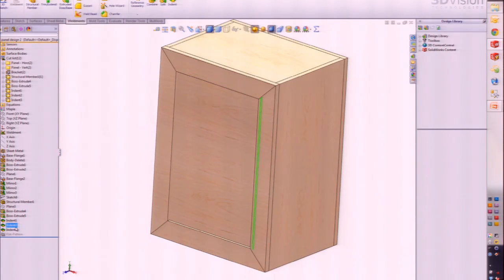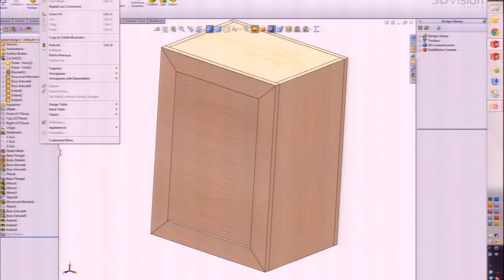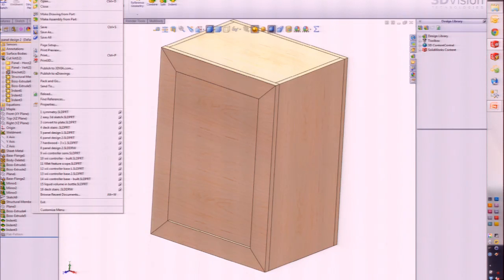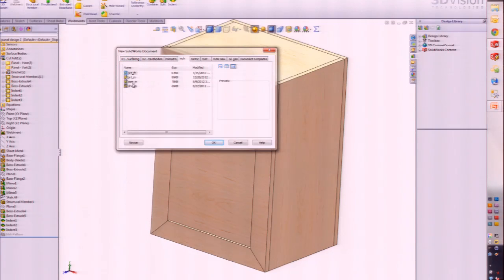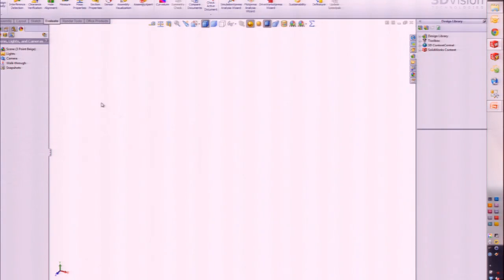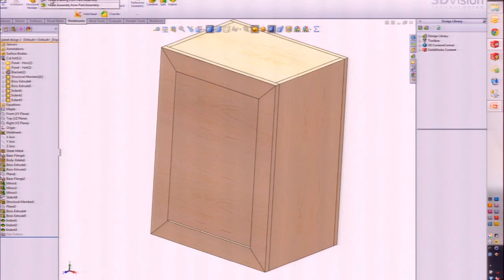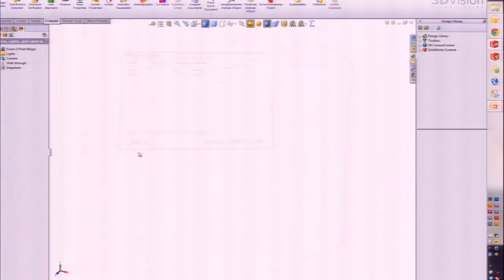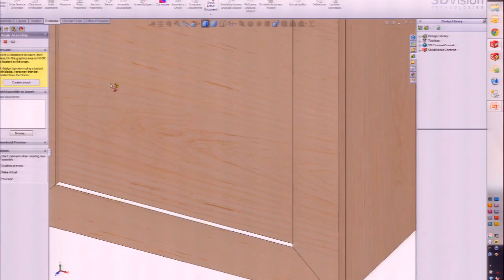But before I do that, I'm missing one more indent feature. And if I didn't know that, here's how I'd check. I'd check for interference. Unfortunately, though, interference detection is a feature that's only available in assemblies, okay? So what's the workaround? I'm going to insert this file into an assembly. Just plop that in. It doesn't matter where it's located. Where'd it go? There it is.